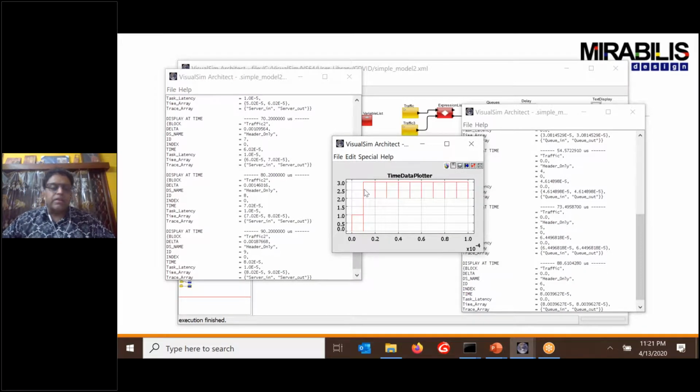What's happening? The first task completed, and then the second task never came along because it's been queued up. But then you start noticing the third task starting to fire here. Why did that happen? It happened because it has higher priority, and before that task was finished, the next request had already come for that particular flow.